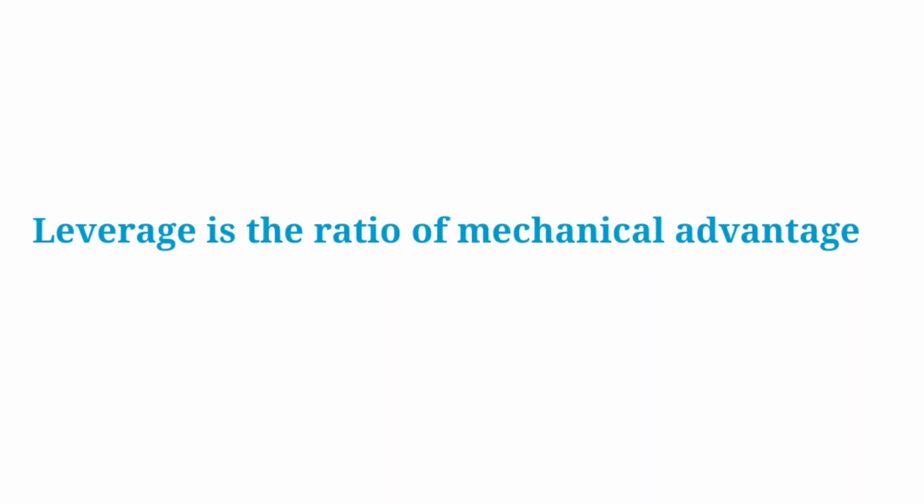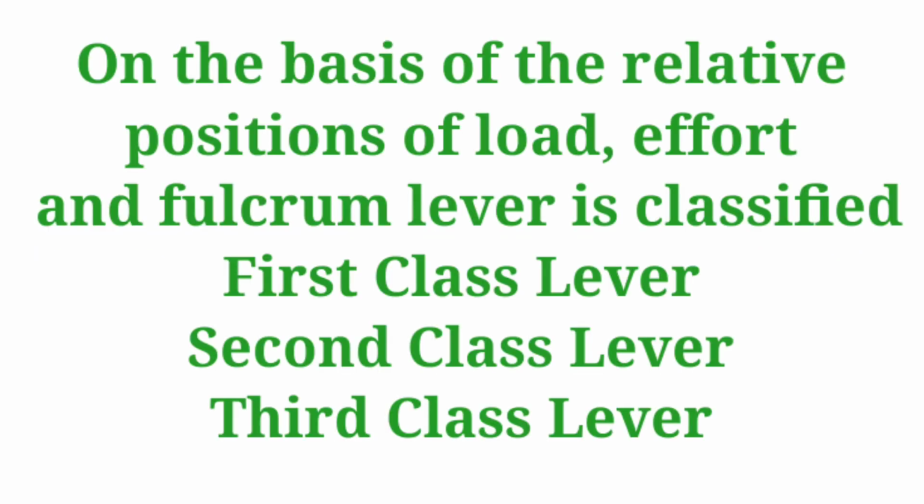So this is the principle of a lever that states the product of the load and the load arm is always equal to the product of the effort and the effort arm. On the basis of the relative positions of load, effort and fulcrum, lever is classified as first class lever, second class lever and third class lever. Sometimes we call it class 1 lever, class 2 lever, class 3 lever.